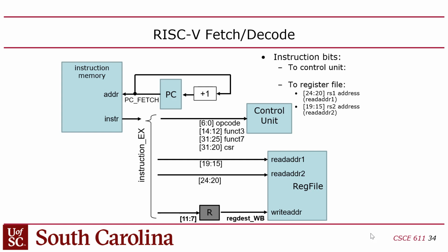All the RISC-V instructions use the same bits for the source register and the destination register. So bits 11 down to 7 is the destination. However, there's a caveat for this one because reading the registers is part of the middle cycle, the second cycle, but writing the result is part of the third cycle, the write back. So you have to stick a register here, and the register is just one line of code that just says always at positive edge clock, this gets that, whatever you name this and that, right? Make sense?